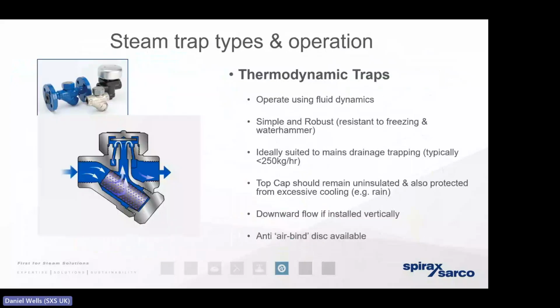So one of the most common, one of the most popular types of steam traps is what we refer to as the thermodynamic or the TD trap. Advantages are it's very, very small, it's very robust. The only moving part is the little disc that you can see fluttering up and down in the head of that hexagonal nut that you can see on the screen.